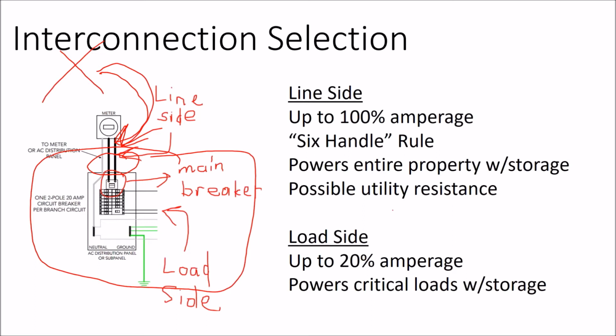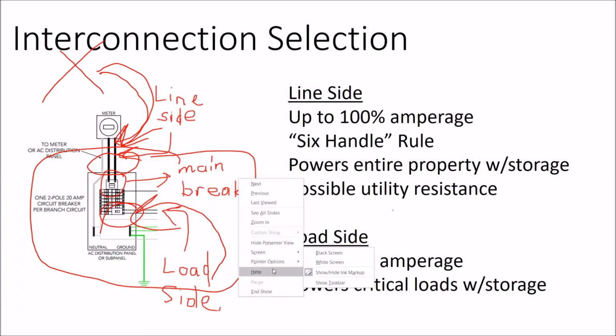Okay, so you can tie it into the line side and not have that backup power if you want to. The reason for that is now that your transfer switch and your generator are all in the same place down the line, it's easier to retrofit a battery bank in addition to the generator if they're all in the same spot in terms of interconnection. But you could have the solar array here and maybe put a motorized breaker and develop your own control system. When you get into batteries and on-site generators, there's a lot of on-site specific customizations for your specific purpose.